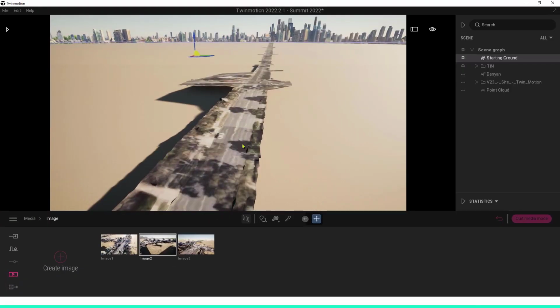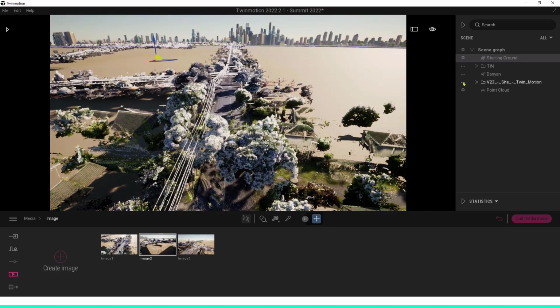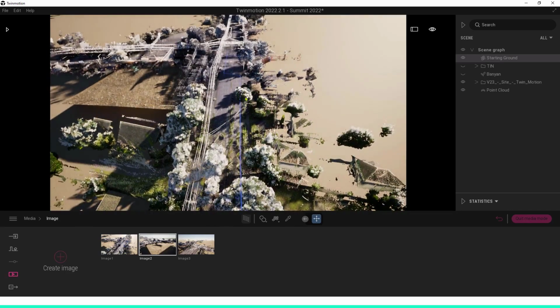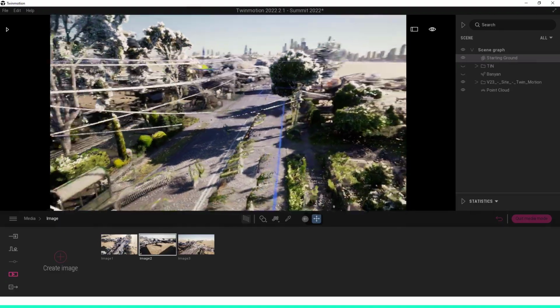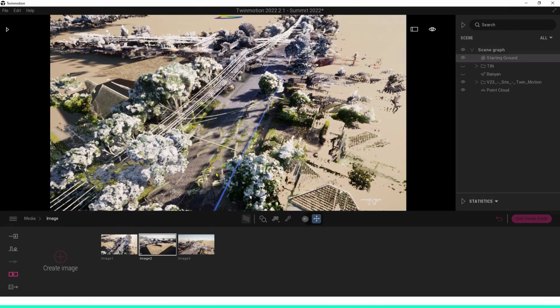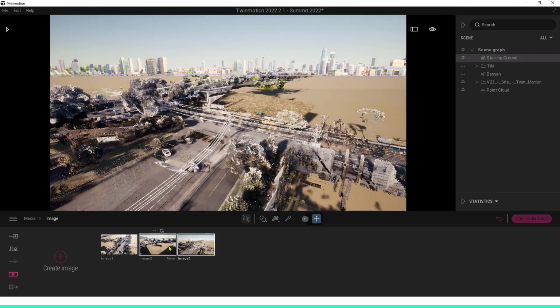And we can see the tin we created from the ground surface with the aerial photo imported from BricsCAD. We can also show the point cloud here. So if I turn on the point cloud, we can view that as well. And also we've linked a separate file with the site and the pipes. So the pipes are shown in X-ray mode, meaning that when we view from above, we can see them through the ground surface. And what we've also done here is saved some existing views, which just provide a good perspective of where the site is located.